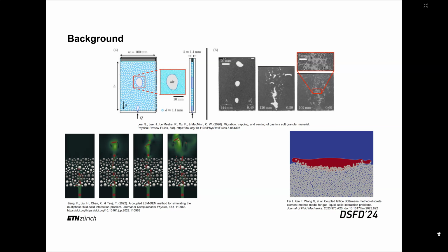In this model, he integrated the pseudo-potential lattice Boltzmann method and the discrete element method, and used this method to simulate drop impact on a deformable porous medium. While in this model, the density ratio is around 20, which is lower than the realistic water-air density ratio. Therefore, in order to simulate more realistic cases, we need a model with a larger density ratio and adjustable wettability.